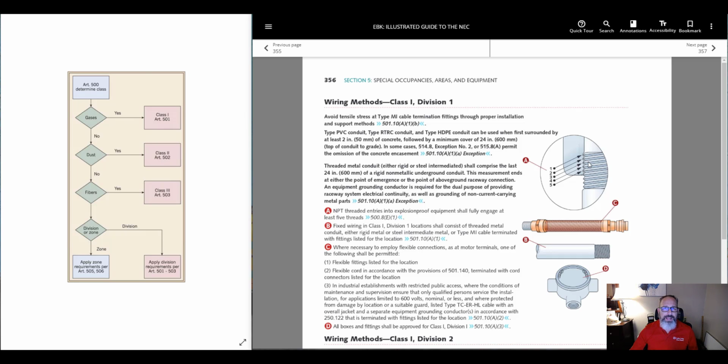A trick that I found was, when a factory piece of conduit, GRC conduit, is galvanized, they galvanize the threads also. And what I like to do was take the threader and run it over really quickly over the threads of the factory end, so that it would screw in easily into the fittings. And as long as you're not going deeper, you're fine. So all you're doing is just taking the outside coating off and you're screwing it together.